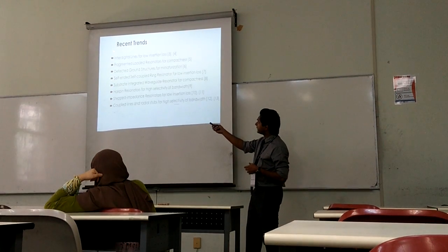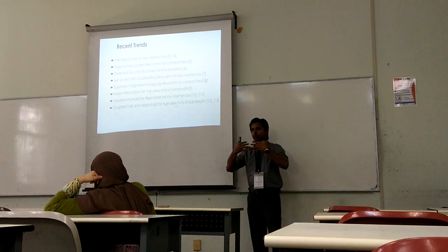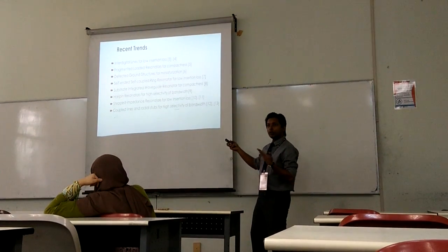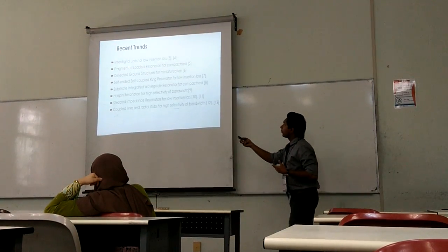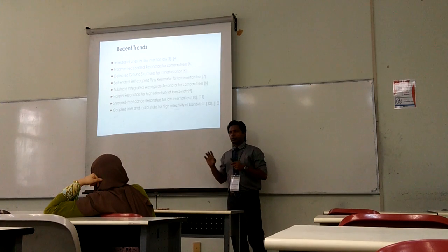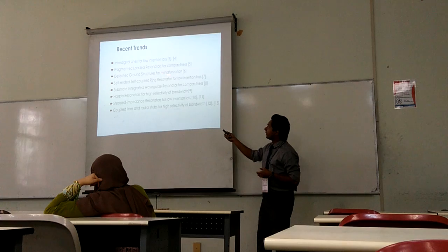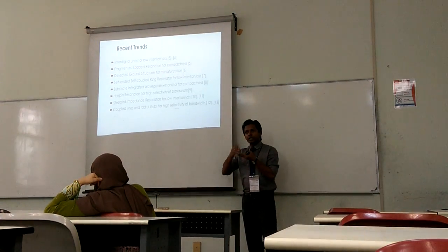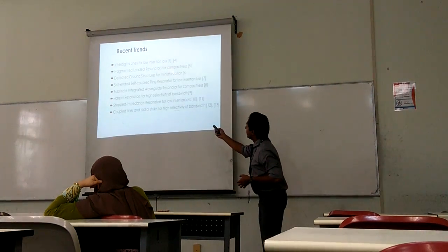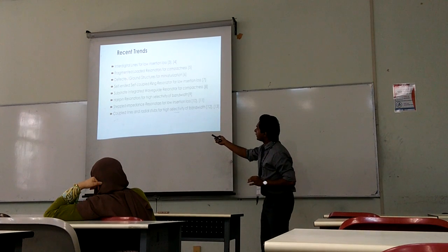One technique is the interdigital lines. You all know this kind of form, interdigital lines. These are mostly for lowering the insertion loss, to get a low insertion loss. Another is the fragmented loaded resonator. I found this in one paper only. I don't know why others didn't use it, but it's a very interesting thing. Fragmented loaded resonators have some spots over the top plane. It's like a fragmented structure, and this is for compactness. This can make your filter very compact, very small size.